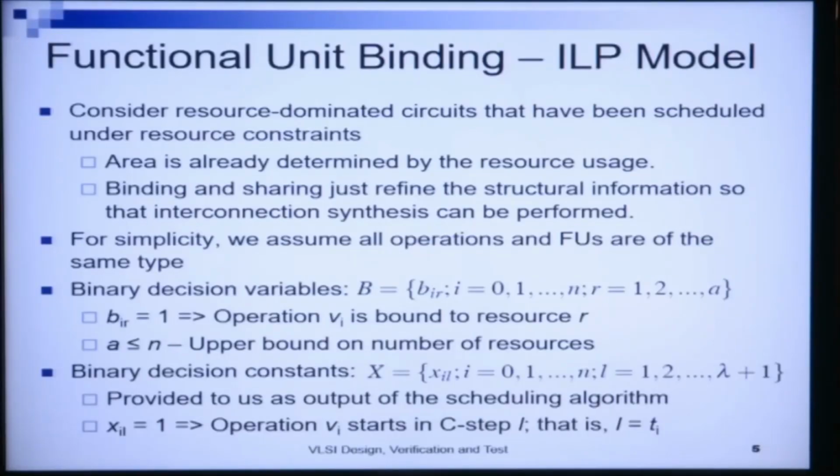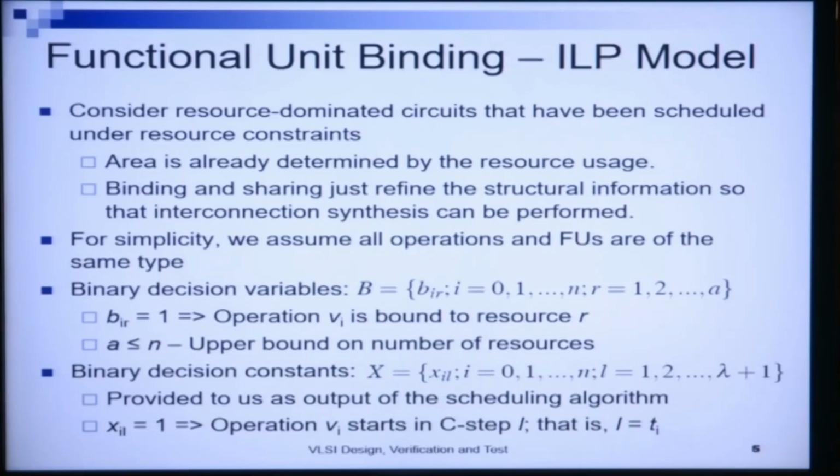By interconnection synthesis, I mean subsequent allocation and binding of subsequent resources. For example, we said muxes, buses, control units, etc. When we have done an actual functional unit to behavioral operation mapping, only then can we solve the subsequent synthesis problems for muxes, buses, etc. Here, for simplicity, we assume that all operations and functional units are of the same type.